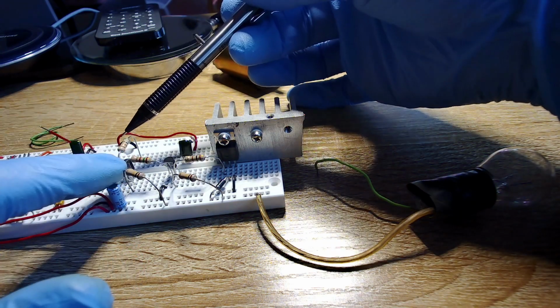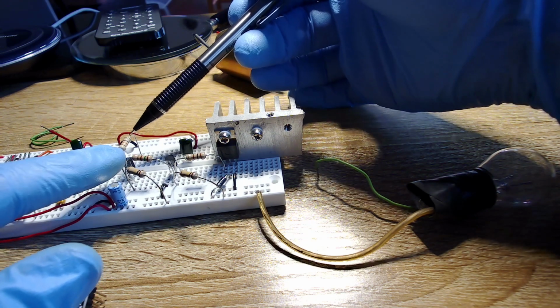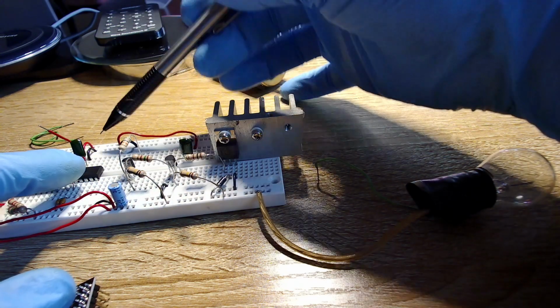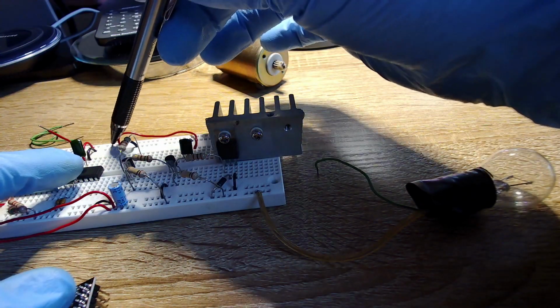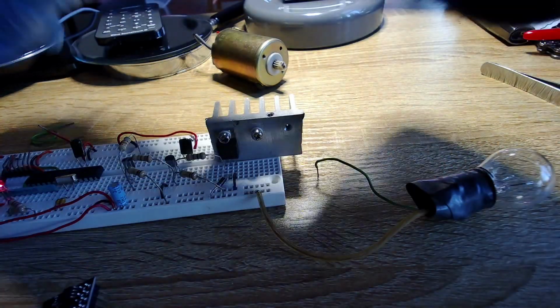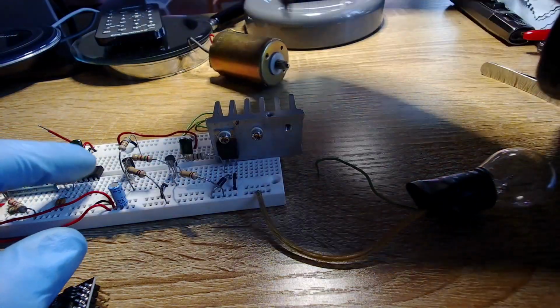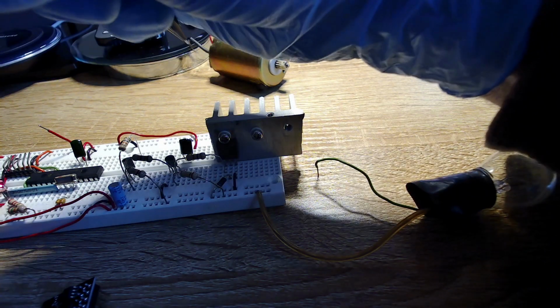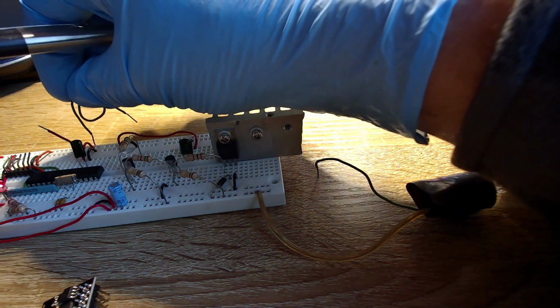Now, I think I mentioned it and kind of left it, but this is a 56K ohm resistor. My point in mentioning that is just take my word for it. This is 5 volts up here, right? So if you put 5 volts across 56,000 ohms, somebody do the calculation. It's going to be less than a milliamp, I think.